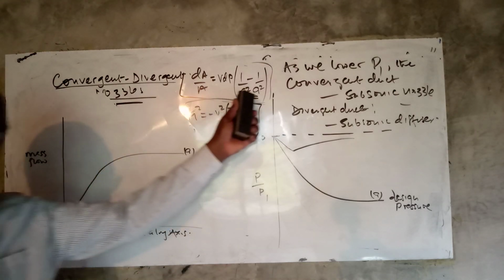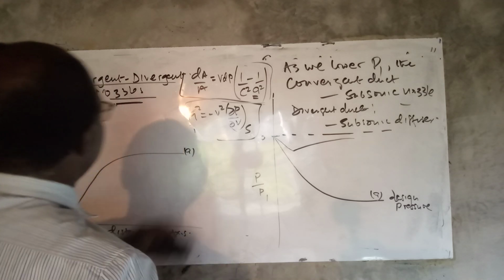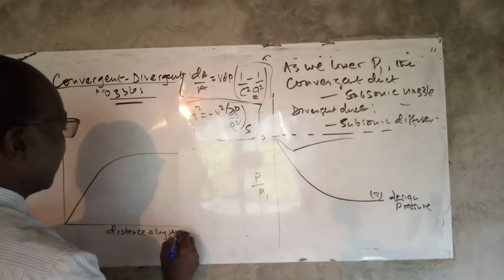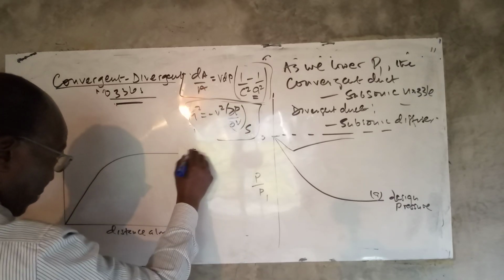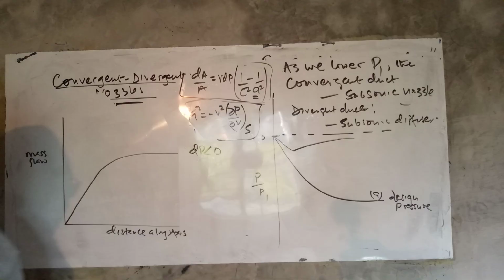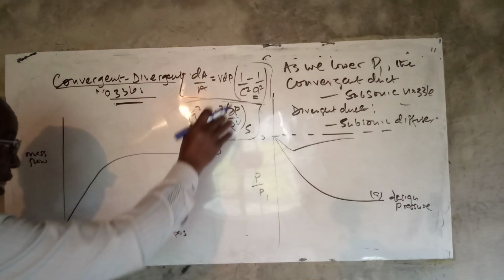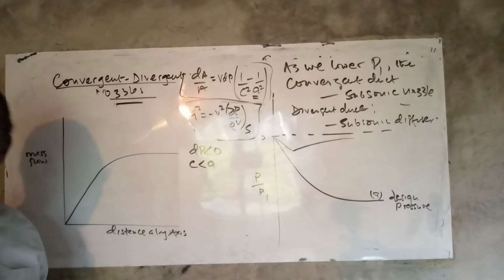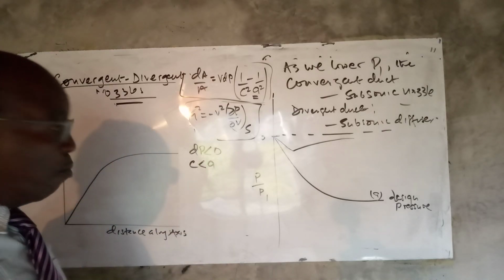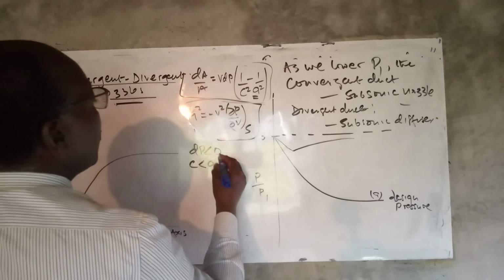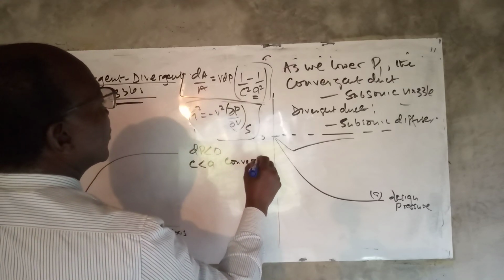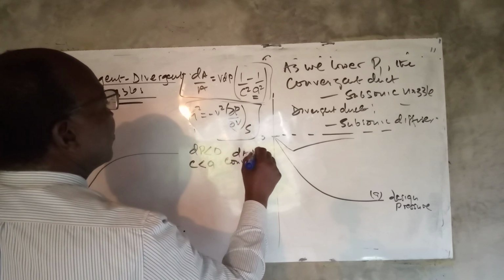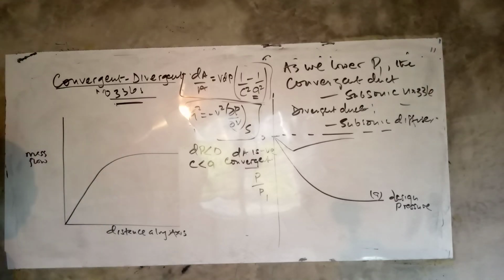And so what is the import of this? The import of this is that when the pressure is reduced, that's when you're dealing with a nozzle. Then in that particular case, when C is less than A, you're talking of the subsonic mode. When C is less than A, that's when we have a convergence, and that is because dA is negative. Remember? Look at our earlier lectures.